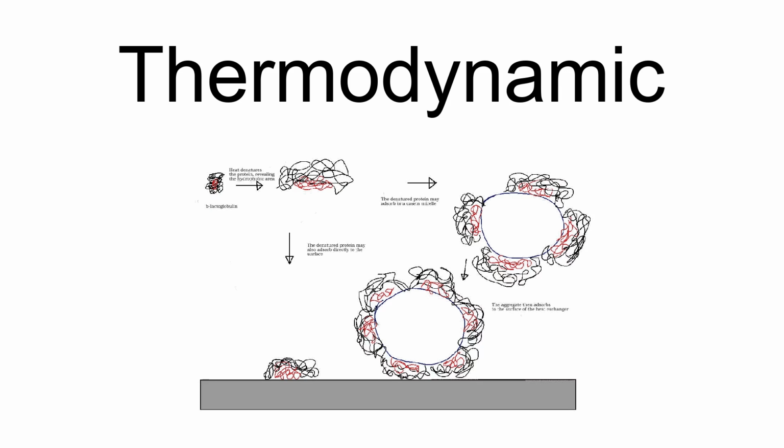As milk is heated during pasteurization, many of the proteins in the milk are denatured. Pasteurization temperatures can reach 161 degrees Fahrenheit, 71.7 degrees Celsius. This temperature is high enough to denature the proteins, lowering the nutritional value of the milk and causing fouling. Milk is heated to these high temperatures for a short time, 15 to 20 seconds, to reduce the amount of denaturation. However, fouling from denatured proteins is still a significant problem.